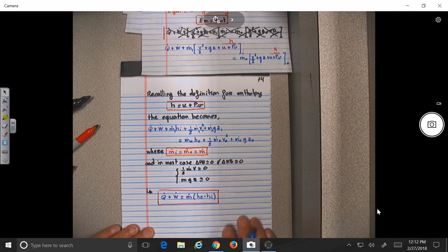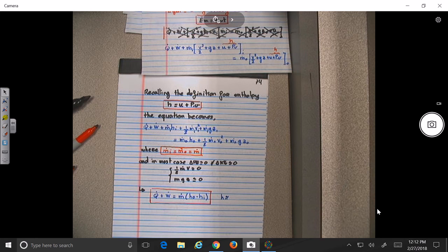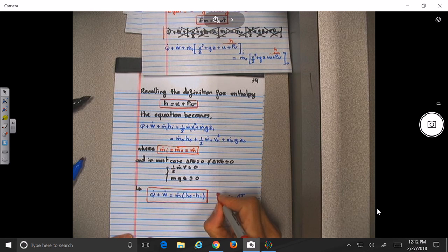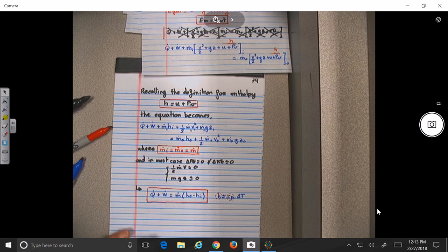So if that is the case, if you remember, H is kind of proportional to what? Remember U, I told you, that's very important. U is related to which one of the coefficients? Specific heat coefficient, we had C sub V and C sub P, no? So something you need to kind of remember, even though you don't understand it yet, is that C sub V is related to what? The internal energy or to the enthalpy? So C sub V is related to the internal energy. C sub P is the one that is related to the enthalpy. So we have this one is the Cp delta T. What I want you to make sure of is that when you see H, think about C sub P. And when you think about U, internal energy, think about C sub V.